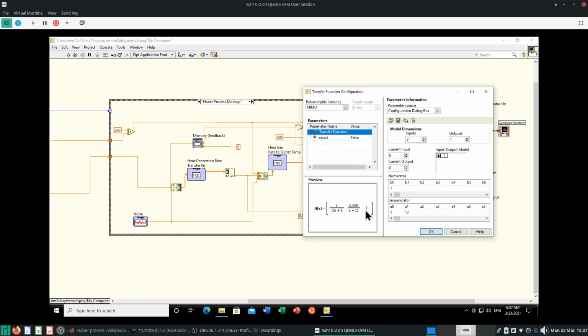The noise, I gave it a unity gain. This is the third input over here. Now what is this second input? This second input connects the reactor power, meaning the chemical reaction is putting out some power. Of course, the chemical reaction plus heat supply translates to some increase in temperature. As your power increases, your temperature increases. So I just give it some, again, arbitrary gain. Maybe this is in kilojoule per mole or something, whatever. But that will result in a gain of 0.005 over some process time as usual.